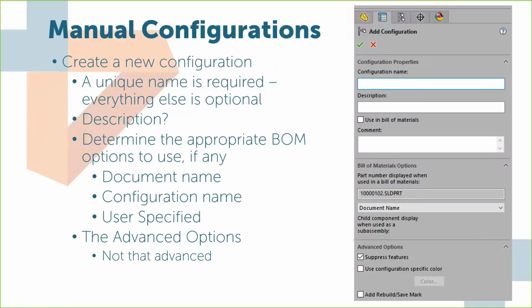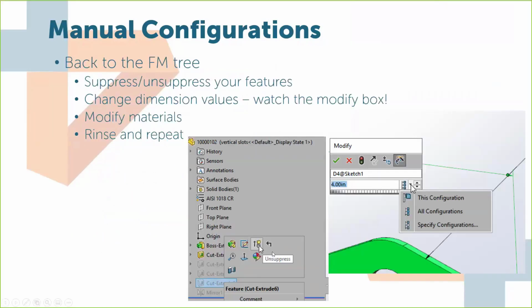If it's off, it may take a few seconds for the software, maybe a few minutes if it's a really complex configuration, to rebuild that configuration. From that point forward, though, that data will be cached for the rest of that SOLIDWORKS session. So that rebuild save mark doesn't really hurt you too much, unless you have really big parts, really big configurations, and you want to speed things up at the beginning.